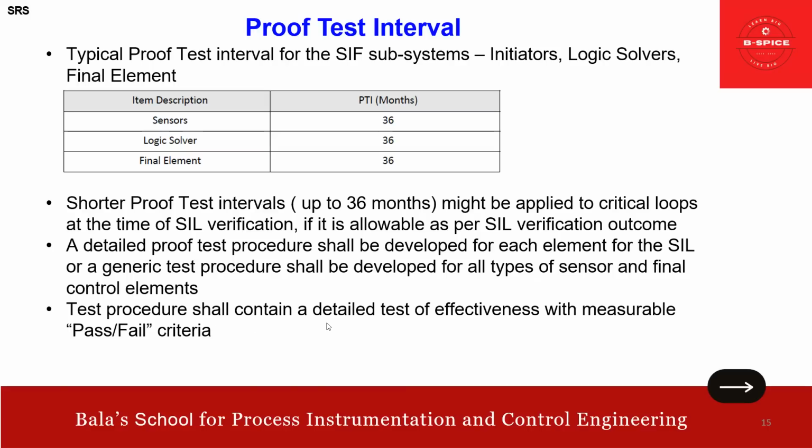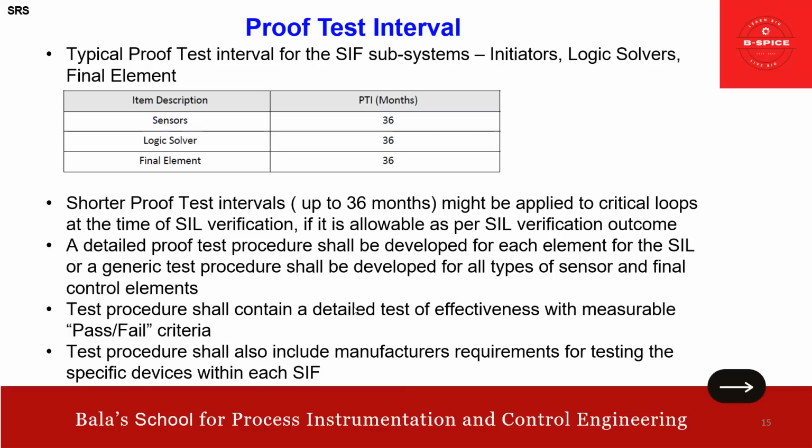Test procedure should contain a detailed test for effectiveness with measurable pass-fail criteria. Okay, all this format we need to put in place, right? Test procedure shall also include manufacturer requirements for testing the specific devices within each SIF. Okay, right. All these need to be incorporated, friends.